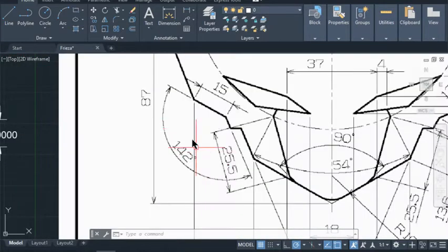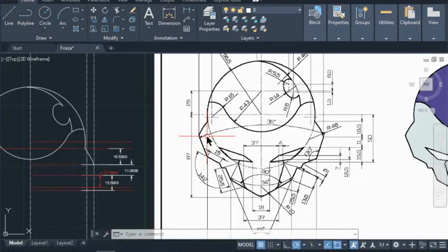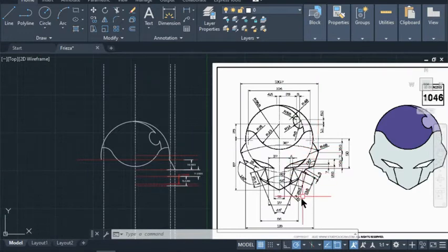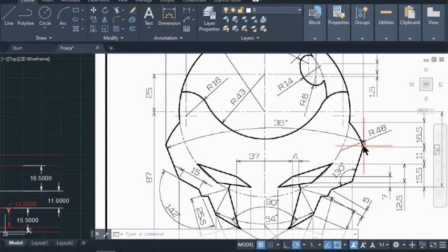Now let's see if there's a measurement on this side. There's no measurement here, so that means it's not the same measurement here. Well, this one has a measurement. There's an angle. All right, so let's take a look here. There's an angle here. That's 36. So if we concentrate on this and keep drawing all the way down to the center line, it's opening a 36 from left and right. So it looks like making a V. So half of that is going to be 18.